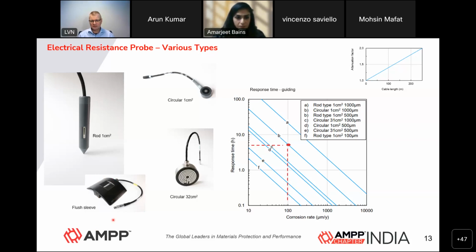But it should definitely get to the same depth of the pipe and definitely get into the same environment and backfill as the pipe. And one should make sure not to use any water when you are installing the probe, because external water would change the chemical environment.